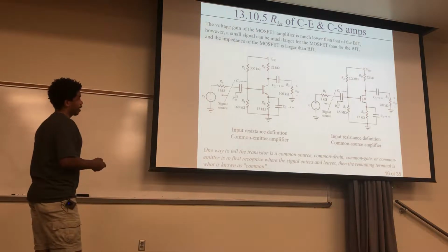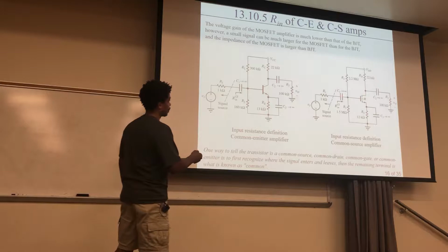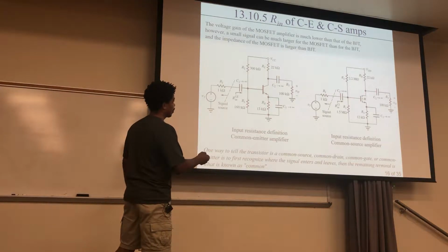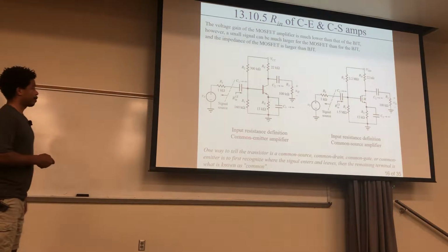Okay, and through AC small signal analysis, this is going to ground right there. It's like an AC ground right there. Similar here. So it's going in through here. Here's the output. Here's your AC ground. Okay, so common emitter and then common source amplifier.